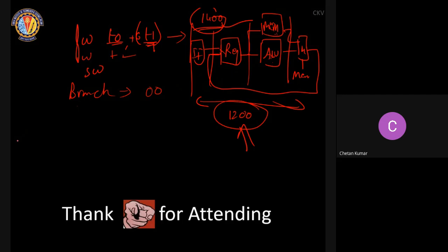And there is one more very common mistake that people have made. The times being different is irrelevant, right? We have to take the worst-case scenario. What is the clock period for the worst-case scenario? That is what we have to look at. You still have to consider the register write, right? Just like we calculated the worst case as the load instruction, and for that we calculated the clock period, you do the same here. Only thing is, since both of them are acting in parallel, whatever is the worst among these will occur only once. So the ALU will not come into the calculation of the clock period, because load will not use the ALU.